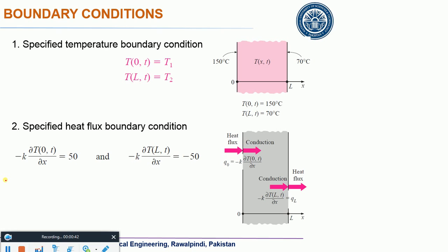We were talking about these few boundary conditions. Just look at this one. What type of boundary condition is it? Dirichlet boundary condition. Okay, why? Because you know what the unknown in the heat diffusion equation is? That is temperature. So if you describe the boundary condition in terms of the temperature itself, the unknown itself, on any boundary, that is a Dirichlet boundary condition.